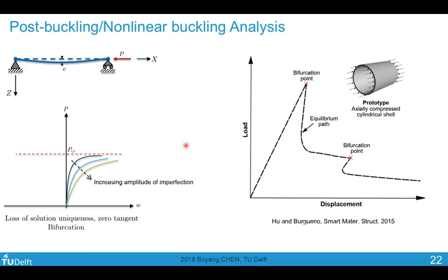In the first lecture, we showed that for this cylindrical shell under axial compression, there is this snapback behavior. And this curve is with respect to a perfect shell. In reality, however, the shell could have imperfections such as non-uniform thickness or deviation from a perfect circle. It would behave something like this.